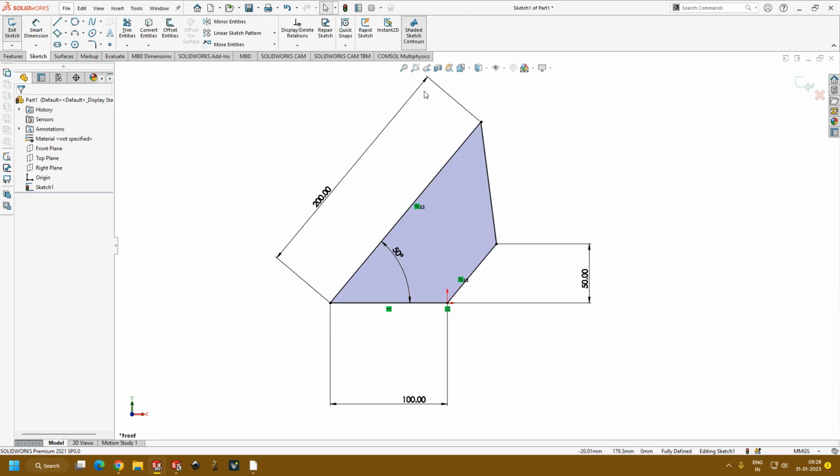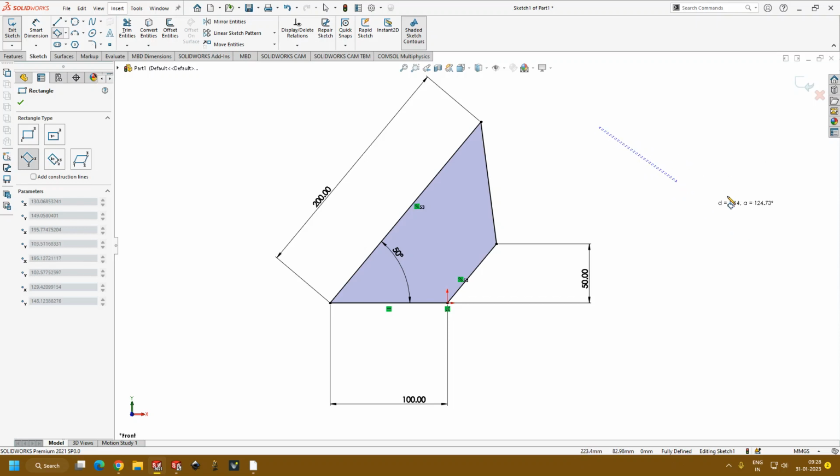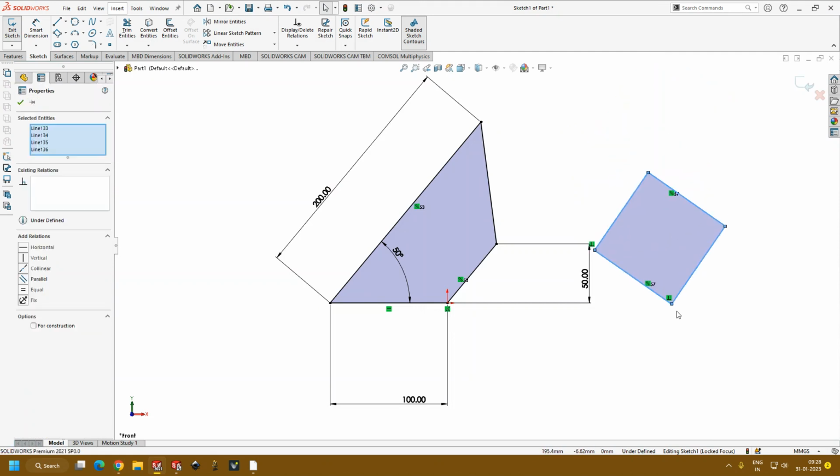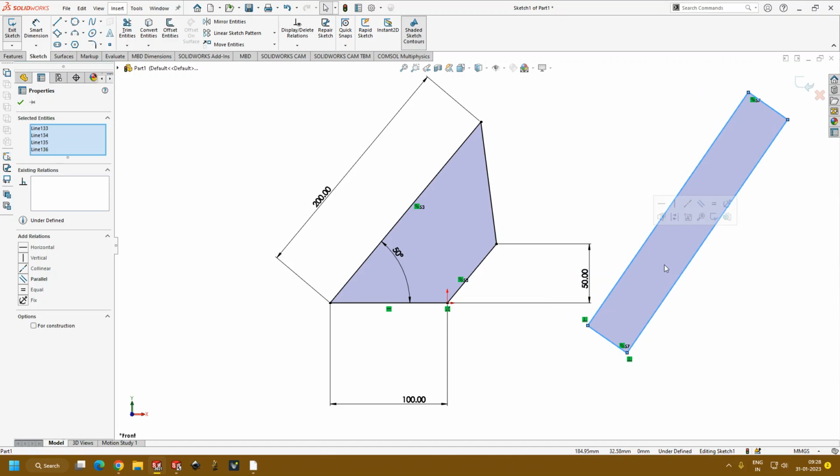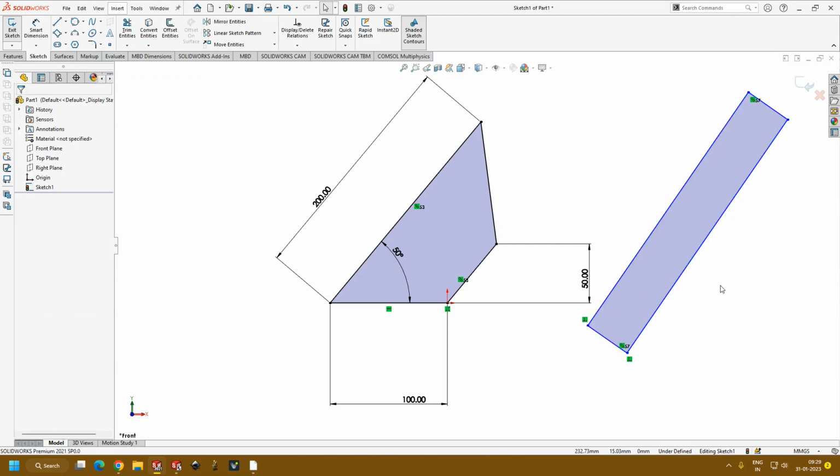For one or two days you will be practicing only constraints. Randomly take any design, leave it in space, and try to constrain it. The foremost rule is constraint should start from origin, and every line should have a dimension. Then identify the blue line, identify how it is moving, and constrain the movable direction. That's it. Simple things.